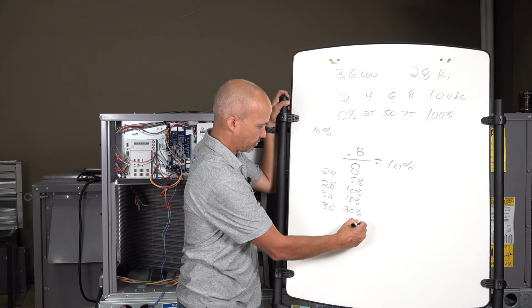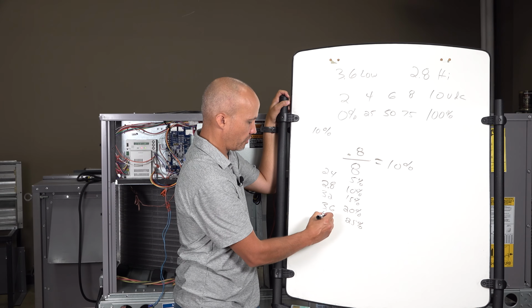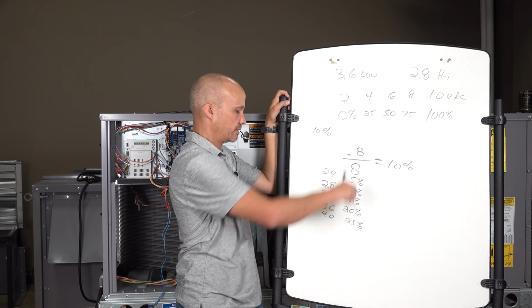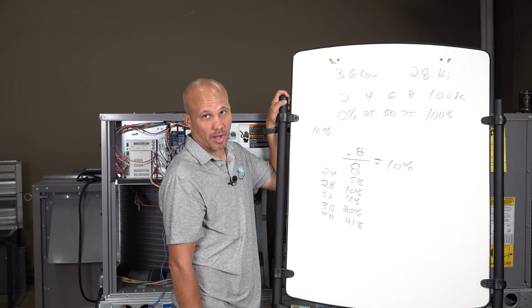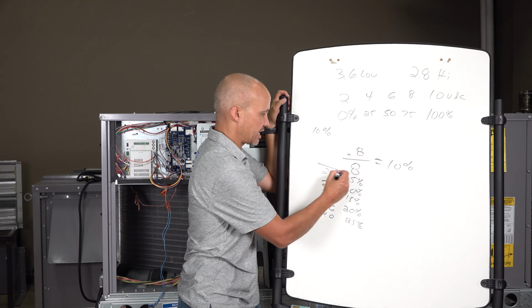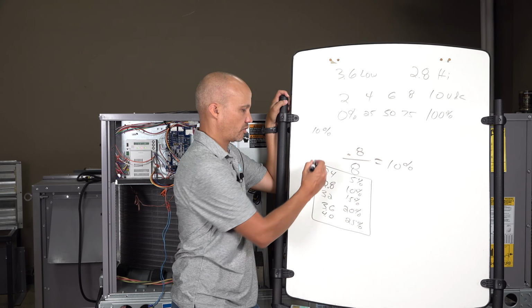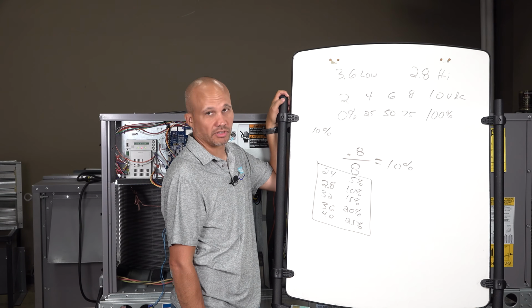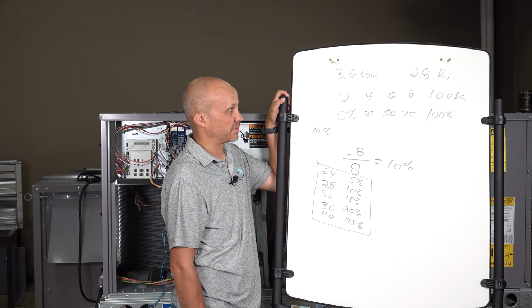25% would be 4.0, right, like we said earlier. And you probably should never have more than 25% on a rooftop economizer, so it can handle that anyway. So if you kind of keep this in mind, or take a picture of that and save it, you don't have to really do this math ever again. But that's the way that works.